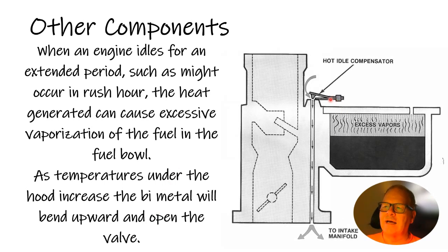But that hot idle compensator is something that most mechanics don't ever think about. And I've actually seen those get damaged, and it'll cause it to run rough, because if that thing's open when it's not supposed to be, it'll make it idle rough and run lean and that kind of thing.